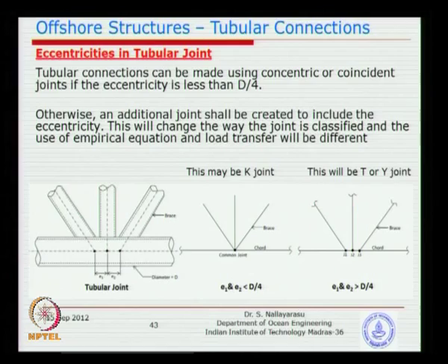If you model this way, on the right hand side, you will see that the member between these two small members will experience a large amount of shear as well as bending moment. So that is why whenever the eccentricity is exceeding d by 4, you should actually design the intersections or the small members between them correctly. That is a recommendation you need to note, because if you forget, you may actually under-design the cord member.